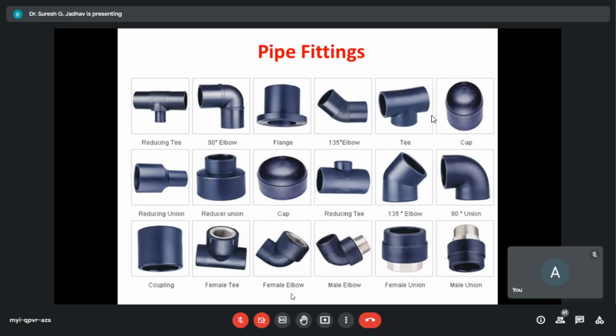And then the next component is a Y bend. So that kind of Y bends are used. Y bends are generally manufactured by MSS-SP, that is manufacturer standards. As per requirement of industry, we can manufacture the Y bends. What is the use of Y bends? For making branch line connection at 45 degree, and T and crosses for making branch line connection at 90 degree. See the difference, Y bend and T's and crosses. With the help of T's and crosses for making branch line connection at 90 degree, and Y bends for making branch line connection at 45 degrees.